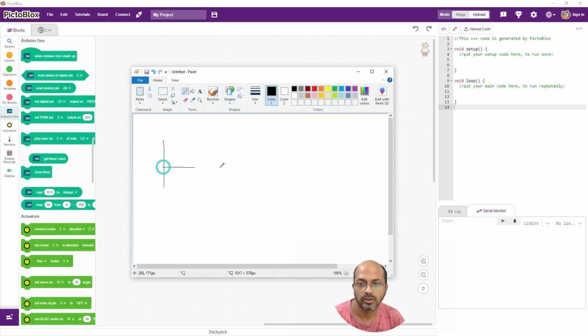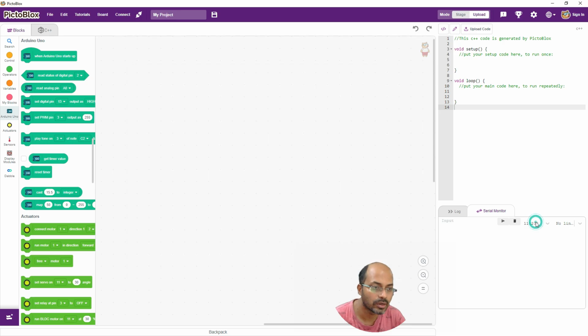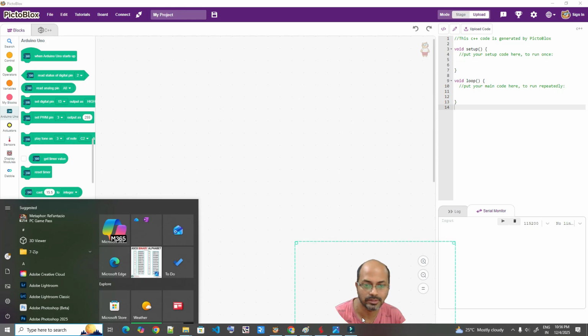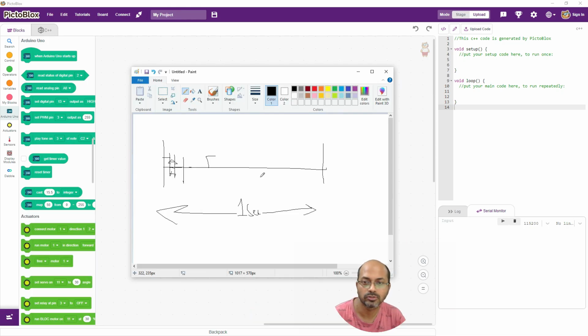You have to take the whole 1 second, and then you have to decide how many pieces to break it into, and each piece will be 1 bit. So this is 0, 0, 0, 0, 0, and then 1. What this bit length will be is decided by this 1 second interval and how many pieces you are breaking it into, and that number is called the baud rate. So 9600, let's take for example. If I break this whole 1 second into 9600, how much comes in 1 bit?